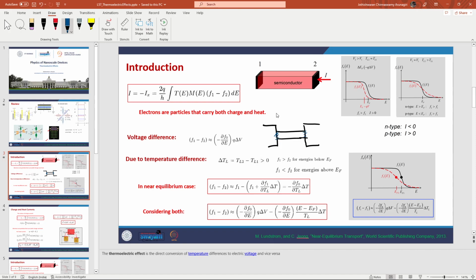That implies that even when we are not applying an external temperature gradient, by virtue of current flow itself, the source and the drain, over a period of time, will obtain different lattice temperatures. So in reality, when we are considering the function of a semiconductor device, even the application of a simple voltage will create a temperature difference, as the device keeps functioning.